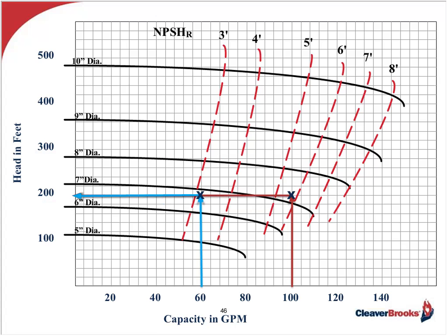Believe me, it does. Also note that changing the operating parameters and conditions of the boiler and associated equipment can also affect the size of the PRV valve, your makeup valve, and safety valves. So being attuned to possible impacts before making any radical changes can certainly save a lot of costs and a lot of headaches in the future.